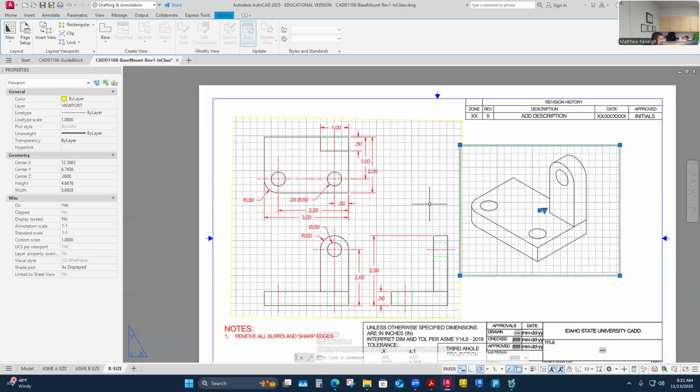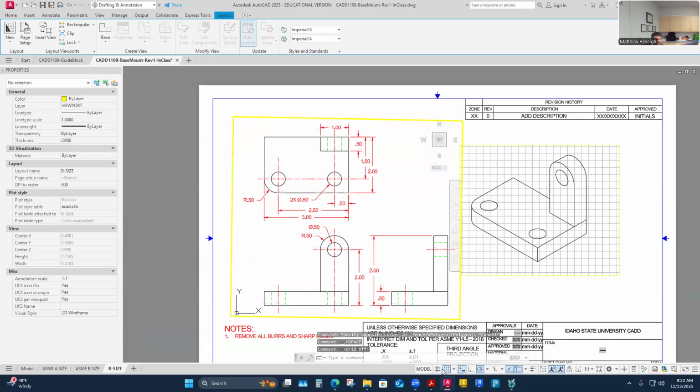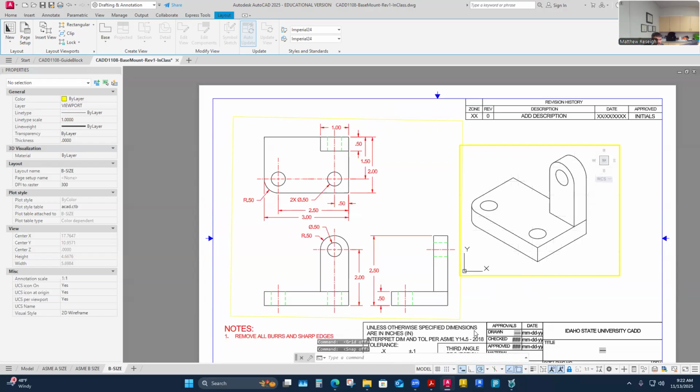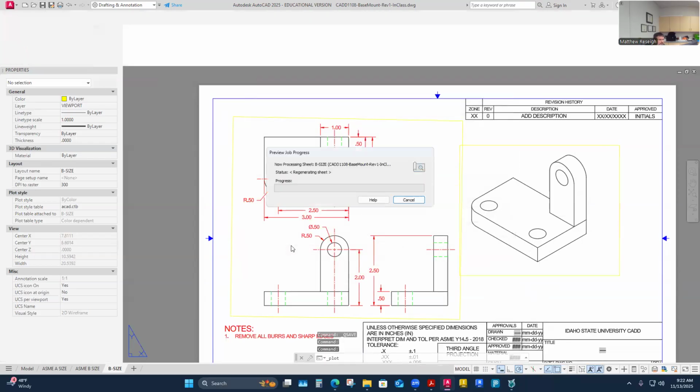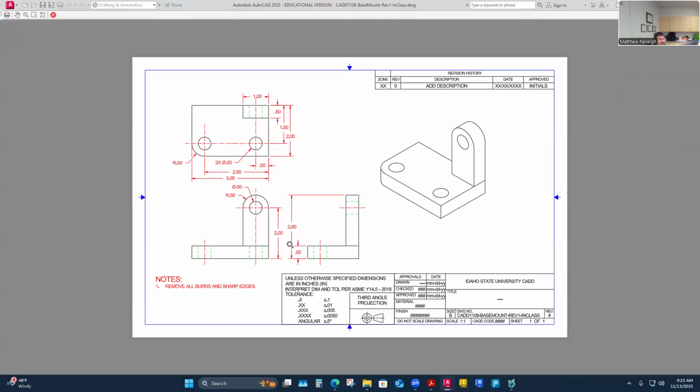That's all it should be, really. I should turn off these grids because they're locked down, this one at 1-to-1. No dimensioning on it necessary. Get rid of that. Do a quick save, and then I'll just check my PDF. And then I'm ready to do my batch plot of this probably, because now it's on here.